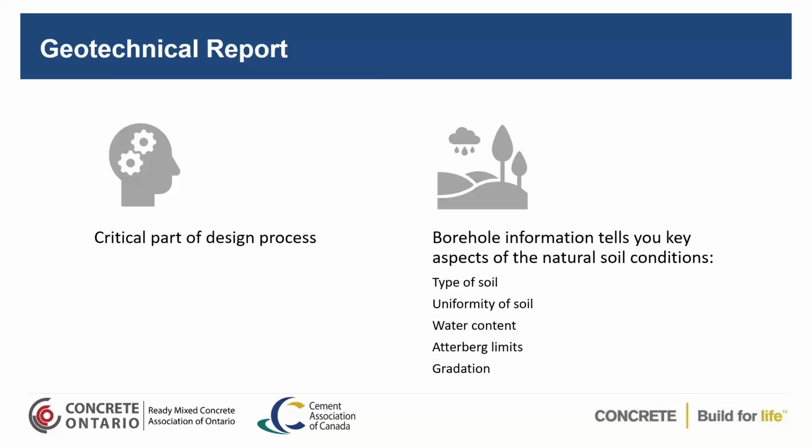So what, in my opinion, is critical to any pavement design is a geotechnical report. You want to make sure that when you're doing your design, you have good information on the foundation that you're going to be building on. That's going to be your subgrade. So borehole logs are very important and have very important information in them. They'll give you the type of soil that has been taken out and tested. They'll give you a gradation of that soil. They'll let you know if there's a lot of excess fines or silt.